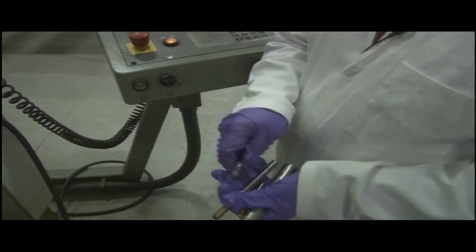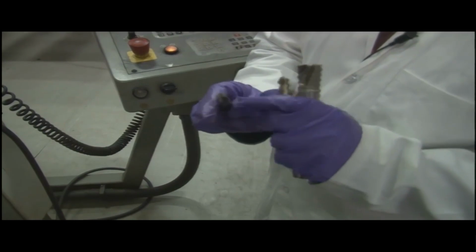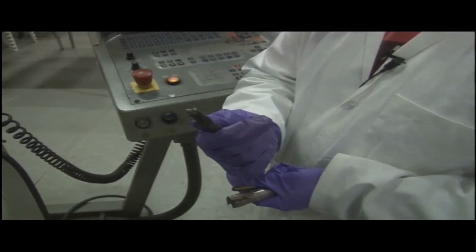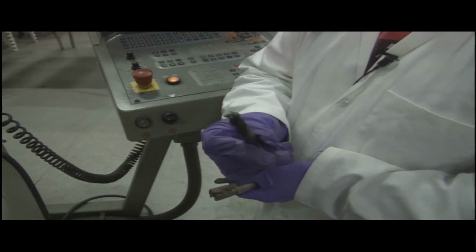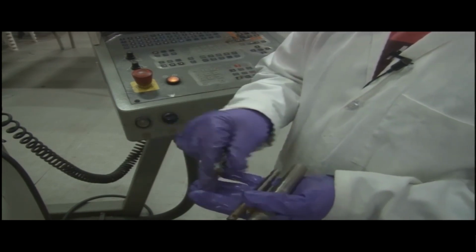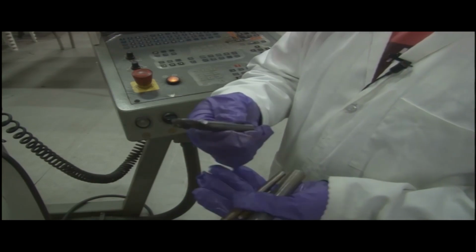Before running the code, we made sure that the references for the machine and for the software are the same, the 0 0 0 is the same. Now, while the machining happens, let us see different kinds of cutting tools here. These are different kinds of milling tools. This is the end mill cutter, where we have cutting edges at the end. It is a 4 flute, or we can say 4 edges, end mill cutting tool. The diameter is 10 mm.